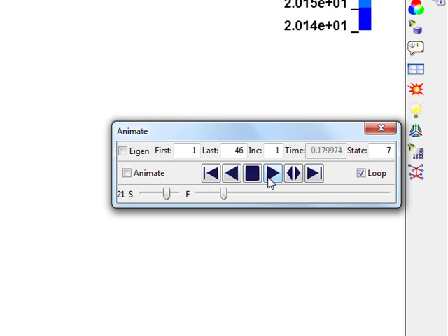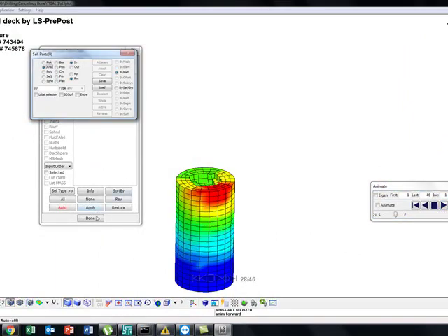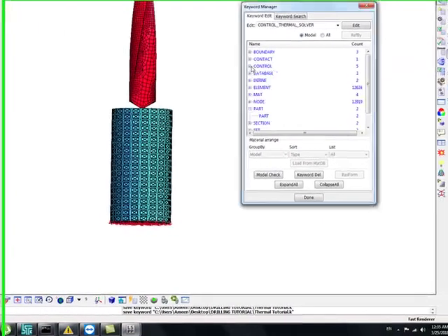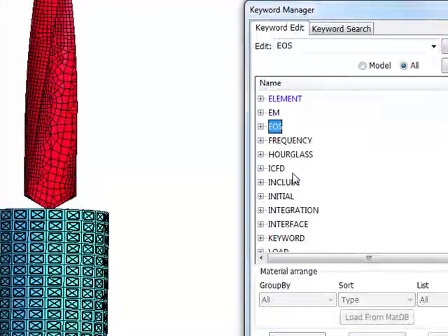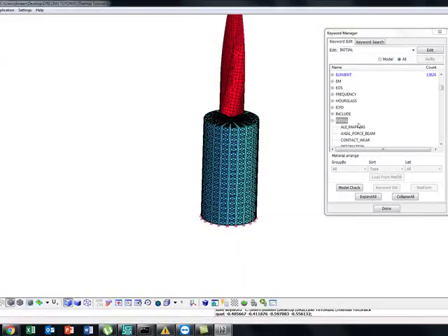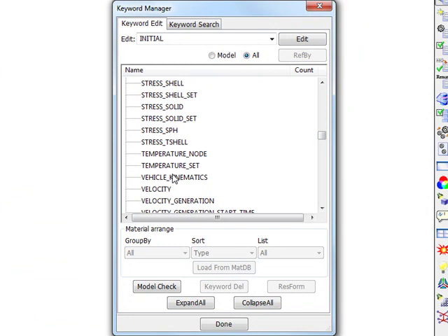There is actually one command that I forgot to put, and that's why maybe I had the error before, and that's the initial condition. So here, what is the initial condition? Initial condition of the thermal analysis. So we need to say initial temperature set.